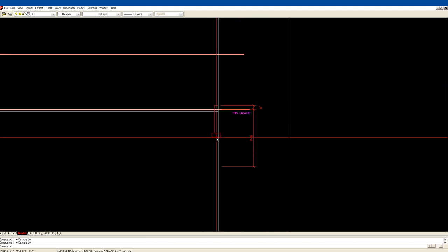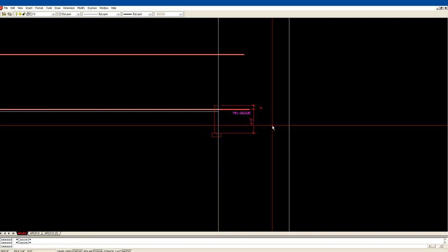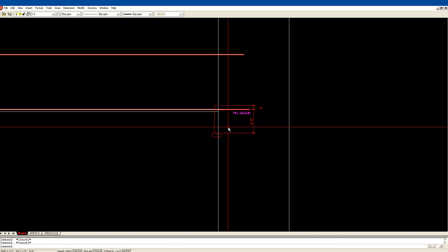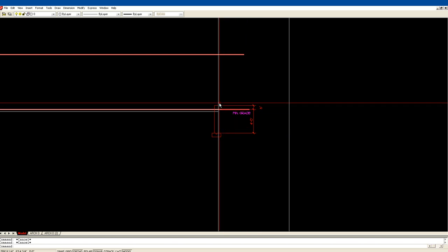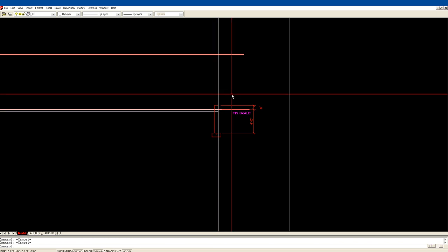So everything's working here now. Hopefully you can see it. I got my 4 feet. Let's change this dimension. There's my 4 feet from finished grade to the top of my footing, so I meet that code. There's my 8 inches. Again, he can move this up or down depending on where he puts his final grade. But for all intents and purposes, we're going to leave it here.